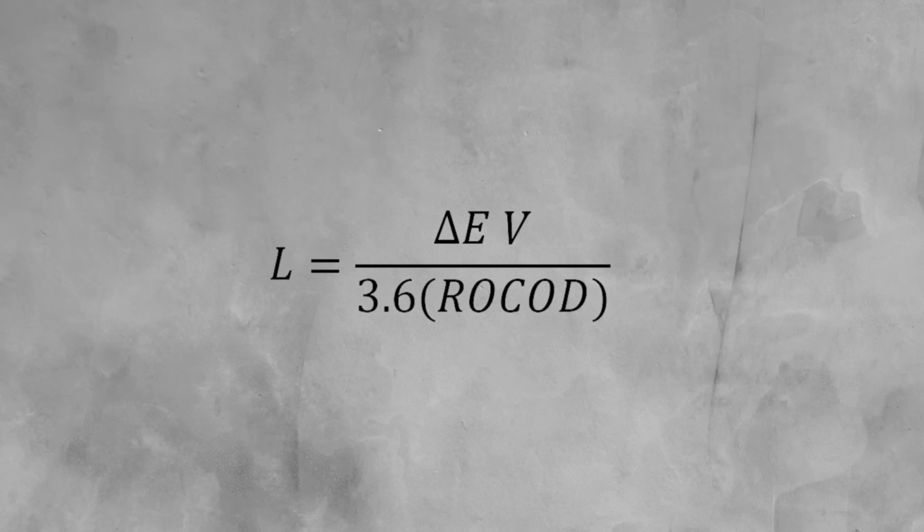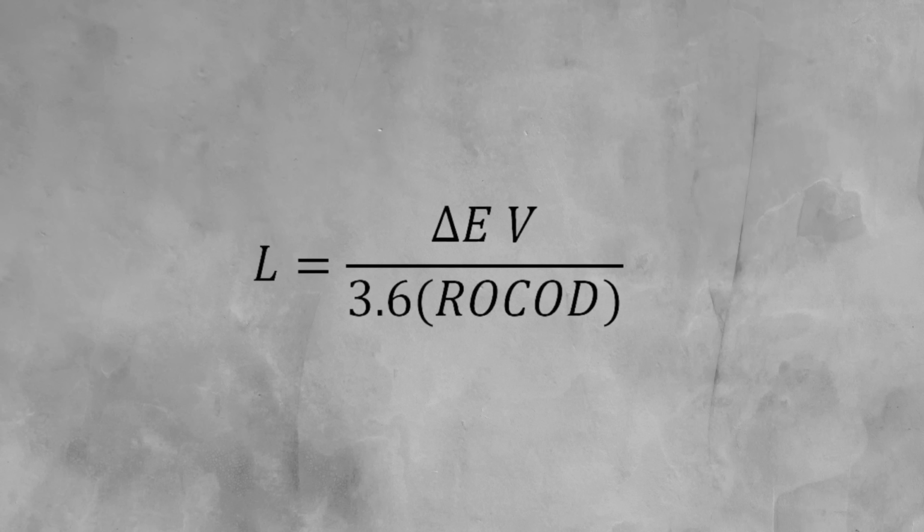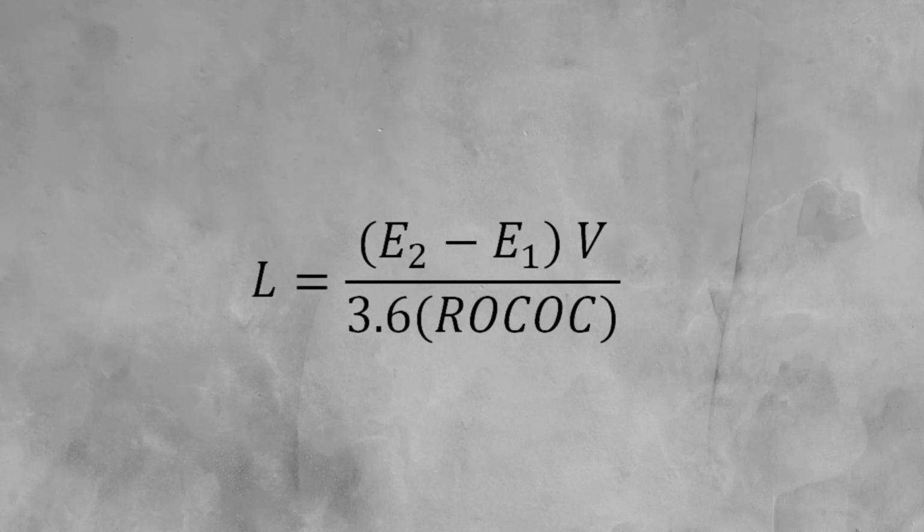We have modified our original formula. As a reminder, we previously used delta E to represent the change between the two cant values. In our example with a straight, the applied cant was the only value, as we started from 0. However, now we need to calculate the difference between the two values. To accomplish this, we can use E1 and E2 as variables and subtract the smaller from the larger. This is the essence of what the delta symbol means. The same approach applies to cant deficiency. We can then calculate the desirable and minimum length of the transition between the two values using the same process.